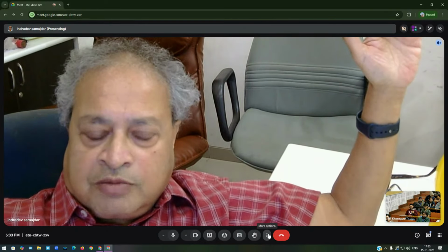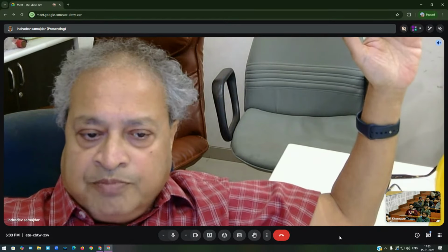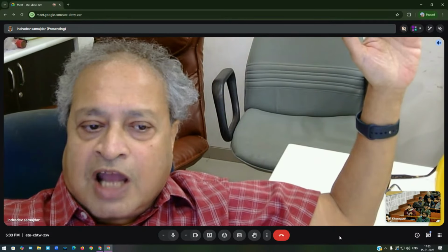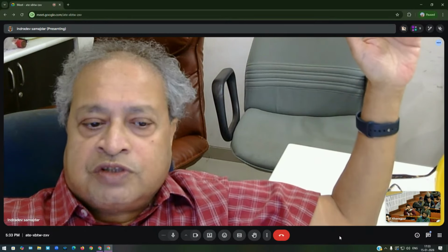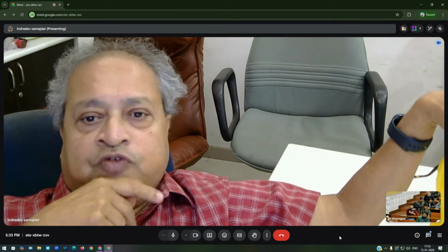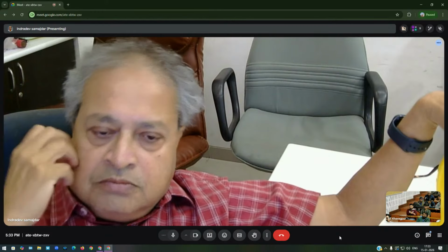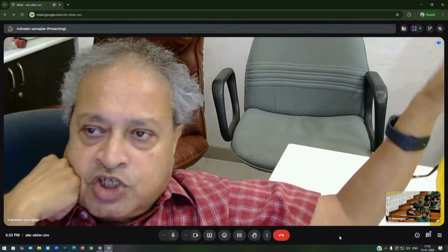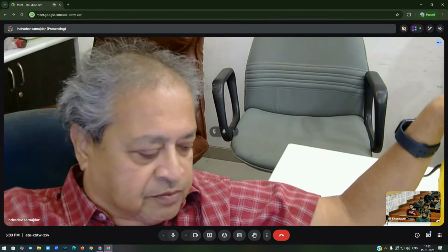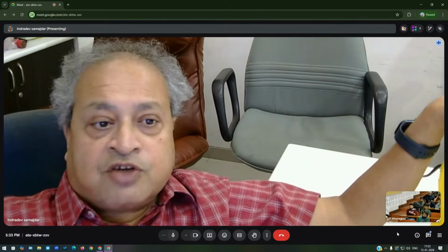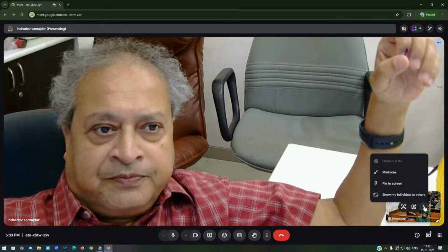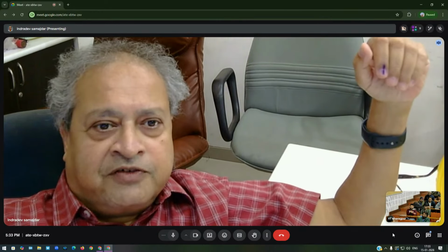Fit a second order moment Fourier series from the slope normalized. And very often we use rho normalized. We don't use the absolute value of rho. Why? Because absolute value has no meaning. So trend in dislocation density can be resolved, not exact quantity. If I told you exact quantity, I think I was daydreaming.